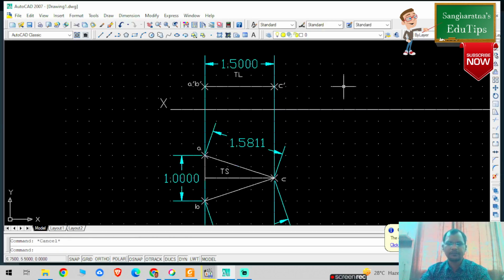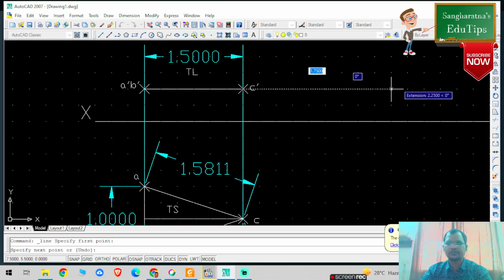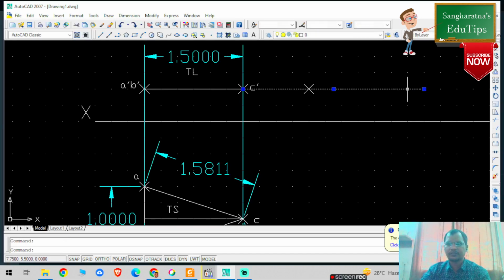So press escape, okay. Once you have converted this dimension to cyan color, draw one horizontal projection from this point, that is point C. You can also call it the locus of point C, locus of point C dash, okay. So select any point on this particular projection line, okay.